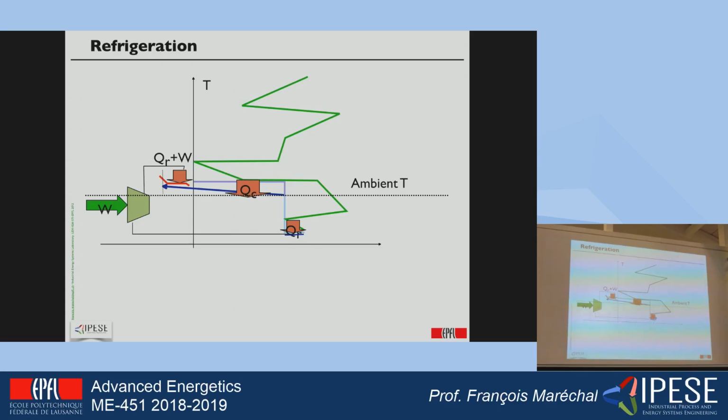Okay? Something which is important here is that I will have to remove not only the refrigeration load, but also the amount of mechanical power that is put in this compressor here. Okay? Because the energy has entered the system and has to be evacuated to the environment.